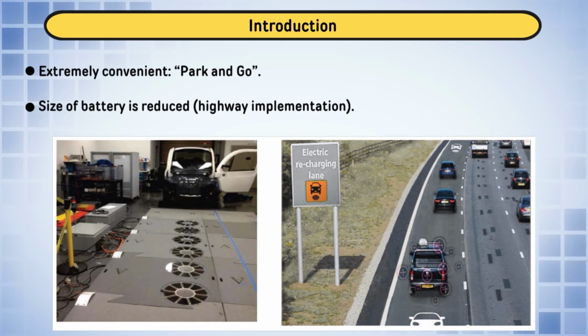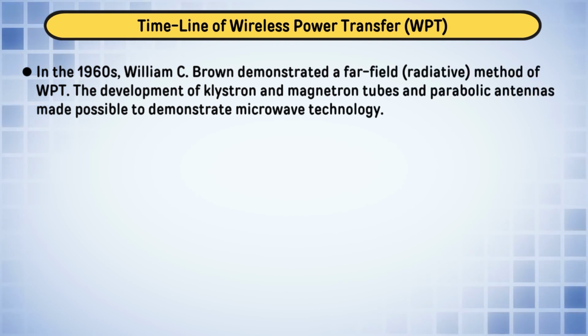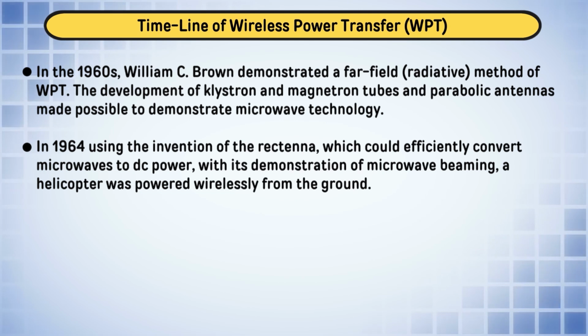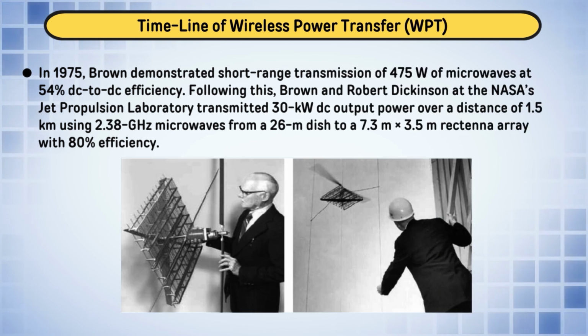In that case, these DC-DC converters are helping to provide constant impedance to the PV module, so that they can see RT, the total impedance offered by this load plus DC-DC converter, is constant, and they can adjust the duty cycle so that the maximum power can be drawn from the PV array.